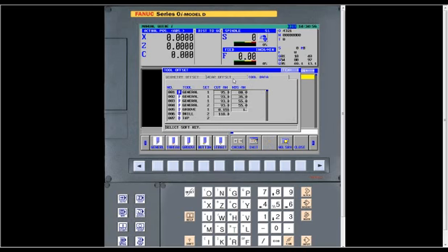All right, now the next tab, tool data. This information is very important for Manual Guide I, because this is where you tell it the type of tool you're using, the cut angle and the nose angle of the inserts, and then also for the simulation, the setting key. So the first thing we go into is the tool type.